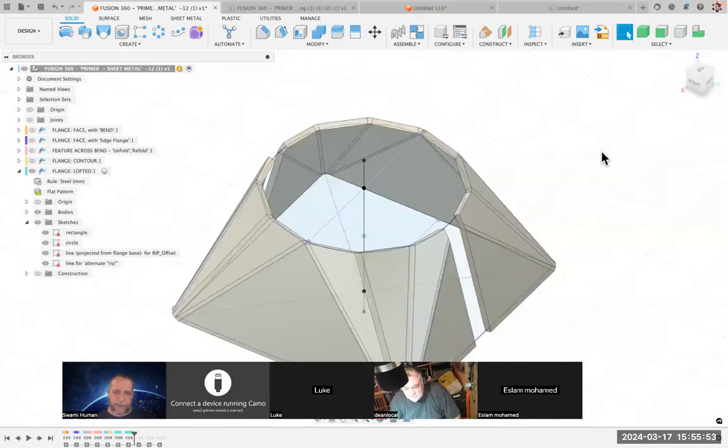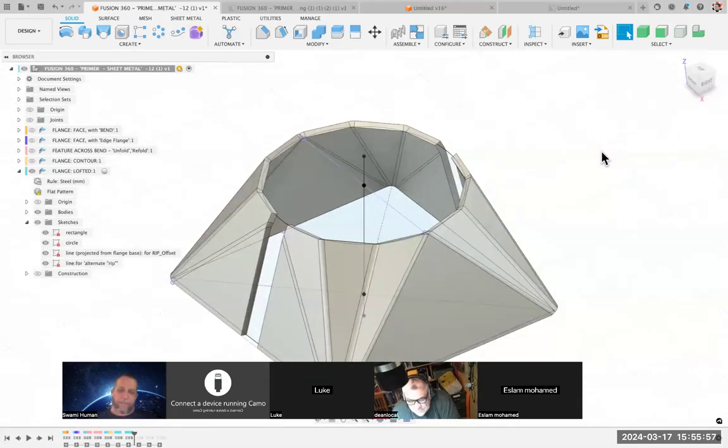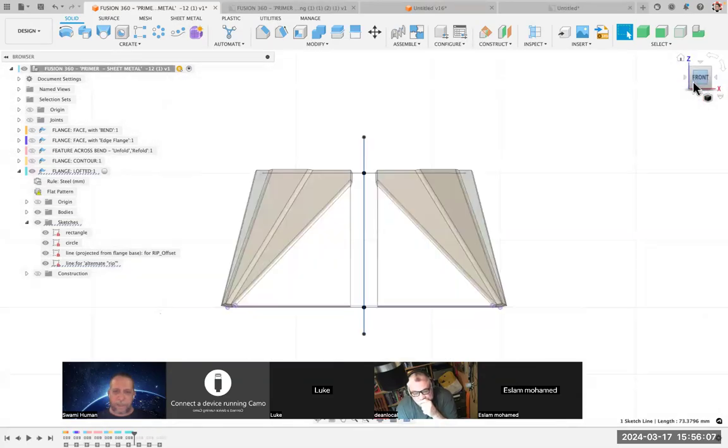Now you see I did the same result on the back face there, but I created a special sketch with that line right there going through from the front there. So I made a special line straight through here, which is where I want my rip, want my cut. Extended it a little bit, so I make sure I cut everything from the top to the bottom because the angles, you might not get it entirely right. And then inside here, I do an extrude cut.